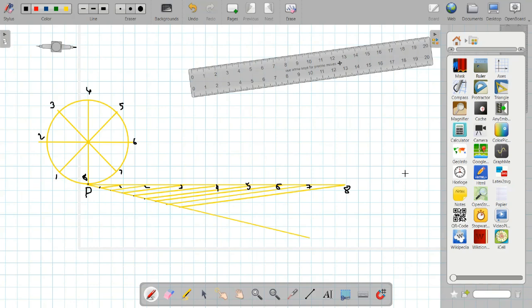Now what you have to do is, from all the points on the circle, again I repeat, draw horizontal lines. Again I repeat, the construction should be very light. Draw perfect horizontal lines. If your construction is perfect, points 3 and 5 will come on the same projection lines.